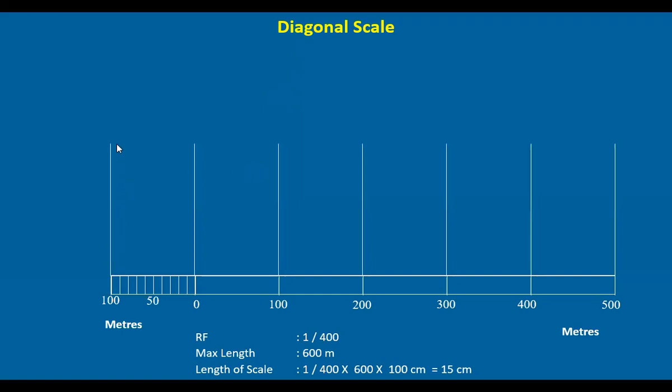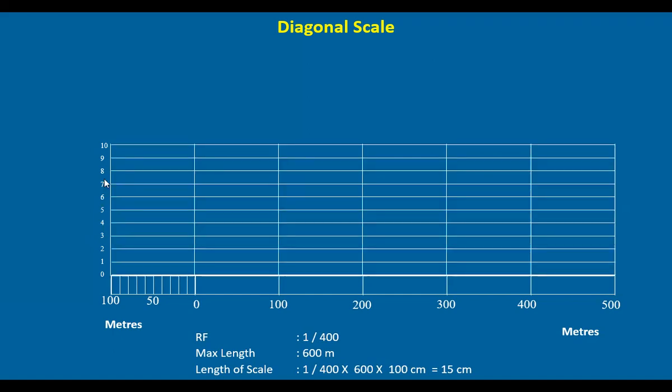So we have drawn a vertical line here, and let us see this. This is 10 meters. To get 1 meter, we have to divide this by 10. So now I take 10 divisions on this vertical scale, 10 points at some convenient lengths. This distance may be some 5 mm or 4 mm, something convenient, depending on the space available here. So mark 10 divisions here. Now draw horizontal lines. Corresponding to this point, all the points can be marked here in the top.